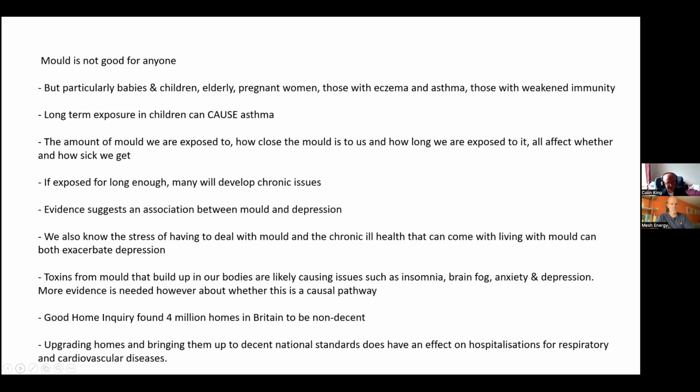So what we're really talking about in a building is moisture balance. That balance between heating, ventilation, and moisture creation, to get that balance absolutely right so that we end up with a good internal environment in terms of indoor air quality and reducing the risk of mould, which is fairly difficult to do at times.